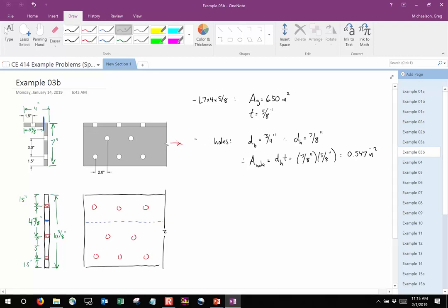And so I'm going to have then 2 failure paths that I need to consider, right? I'm going to have this one, and I'm going to have that one. That second one, I subtract 3 bolt holes, right? How many stagger factors do I add? But, what's the deal? They're not the same, right? It's not the same stagger factor. It's not like the last example where we would add 2 stagger factors, but it was the same diagonal path,